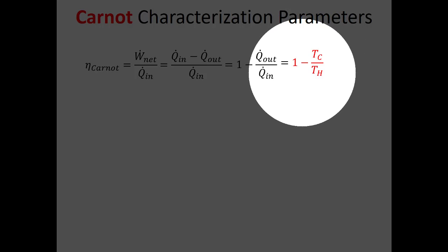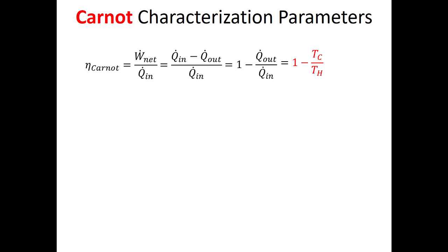So your Carnot efficiency is the best efficiency you can get. So let's say your Carnot efficiency for a particular heat engine is 55%. But you have a salesperson telling you that their efficiency in that case is 60%. They either are trying to mislead you or they don't know what they're talking about, because you know that you can't do better than the ideal efficiency, and 60 is higher than 55.